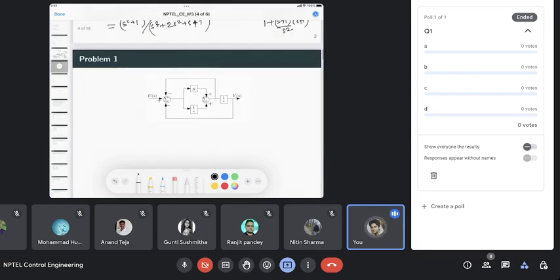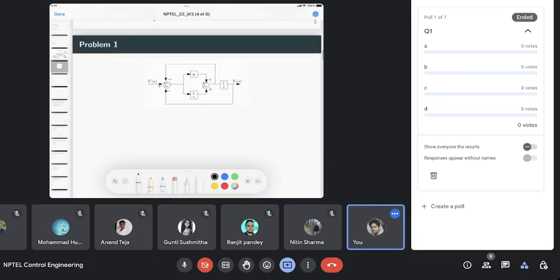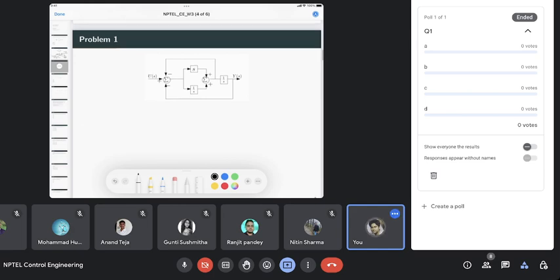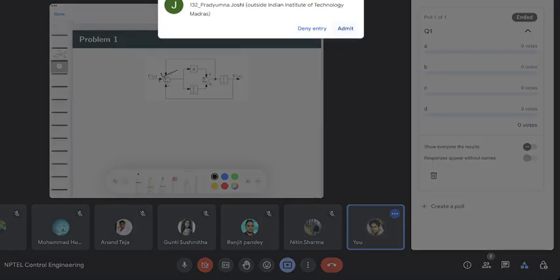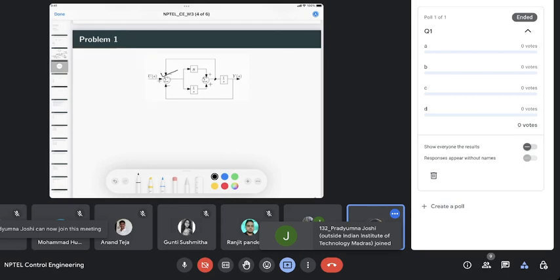So let's try with signal flow now and see whether we are getting the same answer or not. For signal flow, you have to identify the important signals that need to be represented, and you just represent them with an arrow mark with some term, right? This is a block, so that means here we have some signal. This is the summing point, one signal is there. Another signal is this pickup point, and another signal is this, where you are picking this y signal and giving it as feedback. So just write the signal flow representation of that.